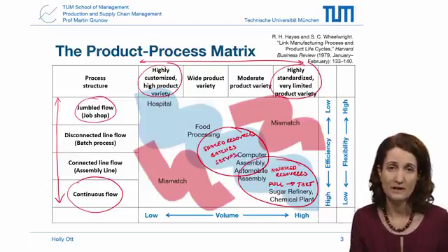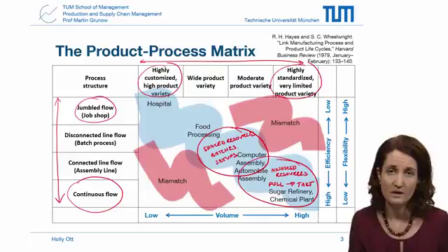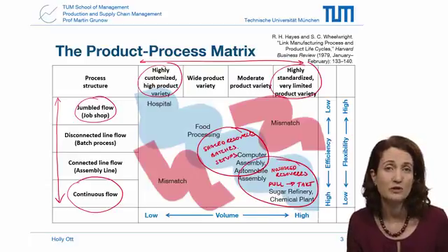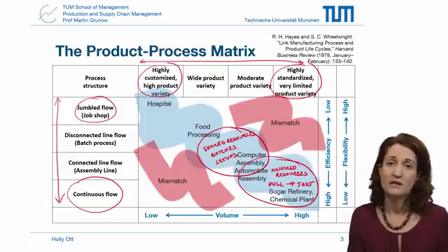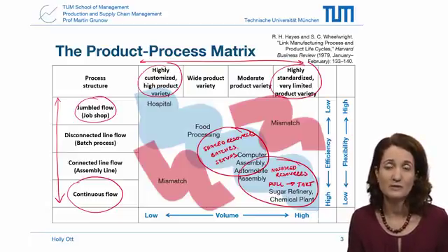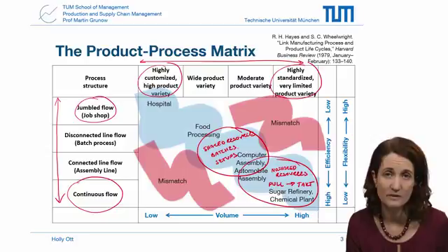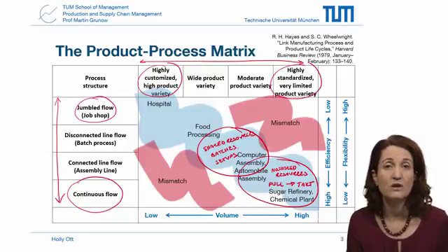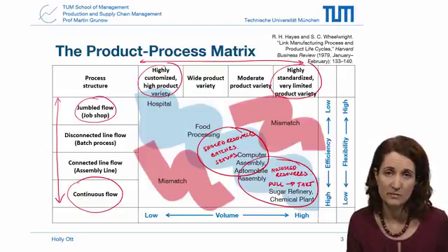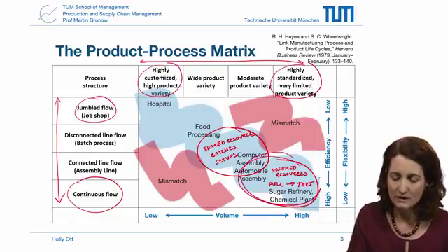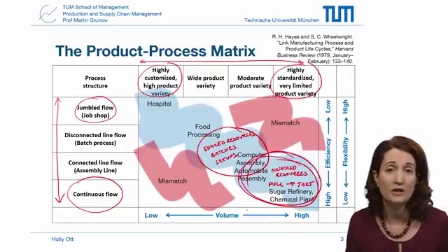Now, most manufacturing is a combination of both. And even Toyota, which developed the Toyota production system over decades, has shared resources in its production. Now, typically, you have more batch processes upstream, while downstream, closer to the end of the production, you would aim for the continuous flow. Now, in our lectures, we are also going to focus on the classical lean model. We're going to be looking at this area where we're scheduling for production with minimal shared resources and minimal setups and changeovers.